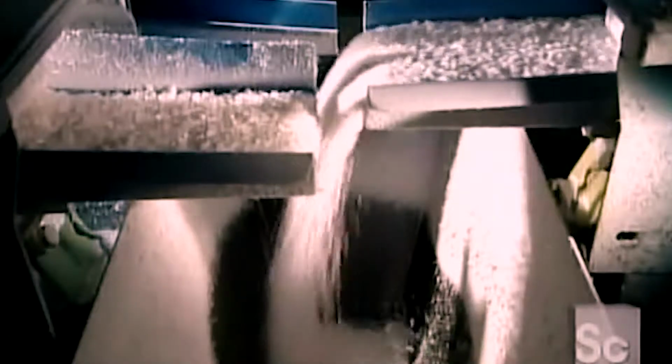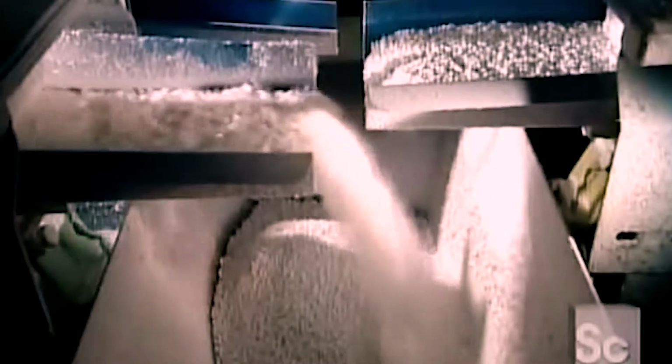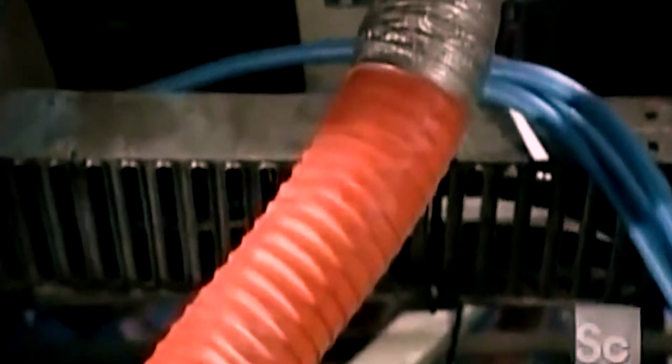First, an automated mixture combines PET resin pellets with recycled plastic that has been reduced to flakes. Plastic loses some of its physical properties when repeatedly heated, so manufacturers must limit the amount of regrind they use, typically capping this ingredient at 10% of the total mix.